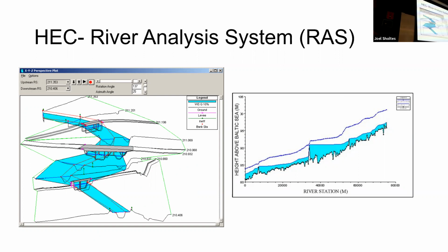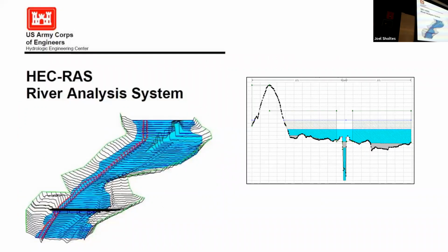Yeah, there is a type of LiDAR. It's called green LiDAR. So it just uses a different kind of laser. It is able to penetrate water to a certain depth. The water has to be pretty clear and not too deep. I think on the order of 2 meters at most. Any deeper and it stops, you start to get some pretty big errors. So it'll work for smaller rivers and streams, but not for bigger rivers.